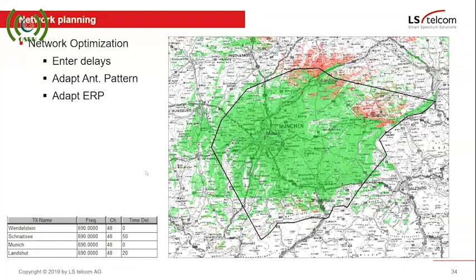Okay, so then there is a further tool you can use. If you sit with the interference scenario in a single frequency network, you can enter delays, and the delays will never remove interference totally. It will only shift it, because if you put in a delay at one point, there will be a bigger effect on the signal in another area. So you only move interference away by entering delays in the feed signal of one of the transmitters.